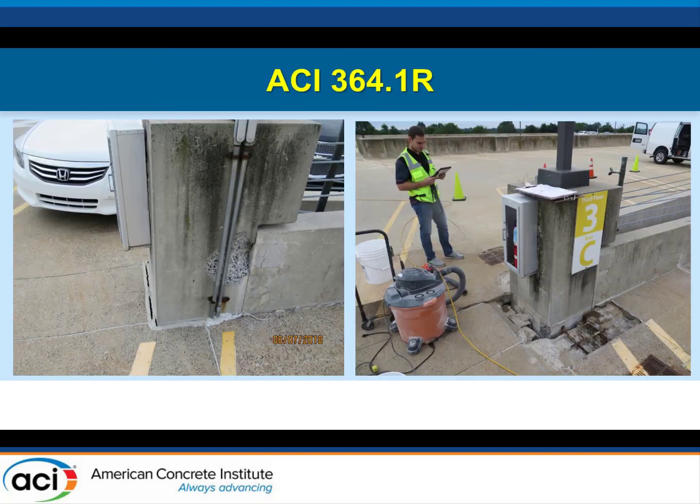It's not unusual. You go through precast, pre-stressed structures, and you see failed sealant joints all over the place. And it's very common that as a periodic maintenance program every 10 years, you replace all the joint sealants in the structure. However, when you start looking closely at the joints, you really need to pay attention to how those seals are failing and whether other things are going on.